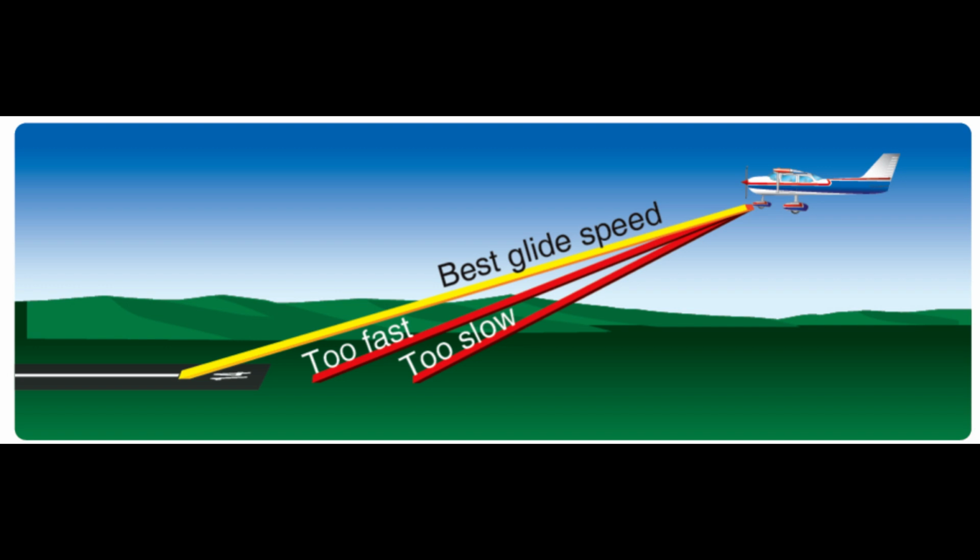Common errors in the performance of descents and descending turns are: 1. Failure to adequately clear for aircraft traffic in the turn direction or descent. 2. Inadequate elevator back pressure during glide entry resulting in an overly steep glide. 3. Failure to slow the airplane to approximate glide speed prior to lowering pitch attitude. 4. Attempting to establish or maintain a normal glide solely by reference to flight instruments. 5. Inability to sense changes in airspeed through sound and feel. 6. Inability to stabilize the glide, chasing the airspeed indicator. 7. Attempting to stretch the glide by applying back elevator pressure.